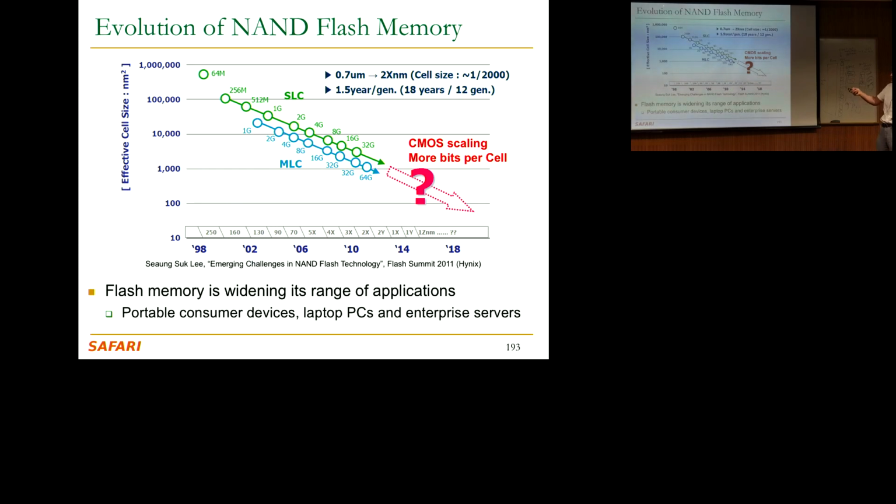This is 1998, as you can see, and this was about 2012 or so. This is single-level cell. We're going to talk about single-level and multi-level. Basically, you can chop the charge voltage range in flash into multiple levels. Either you can say, I have one reference, and anything below this is 1, anything above this is 0, or vice versa. Or you can say, I have 3 different partitions, and I have 4 levels as a result: 00, 01, 10, 11, for example. That's one encoding, of course. You may not want to encode things that way. But this has scaled really well over time.